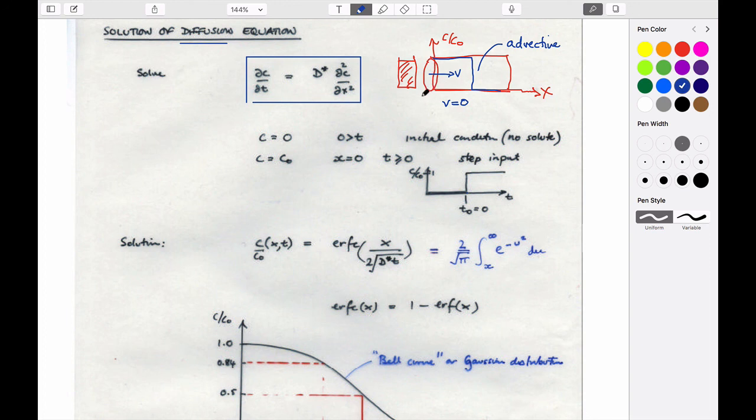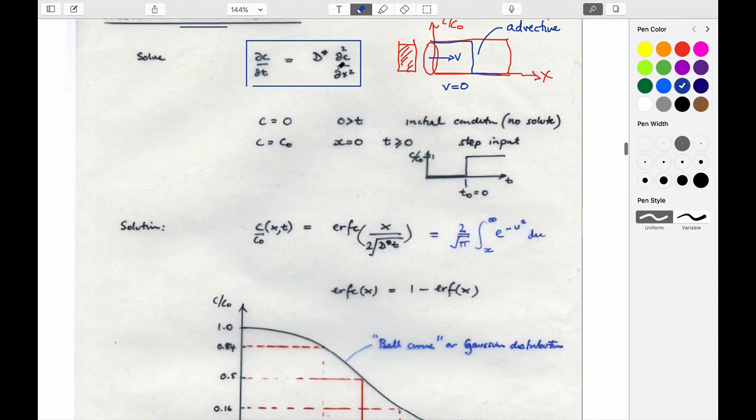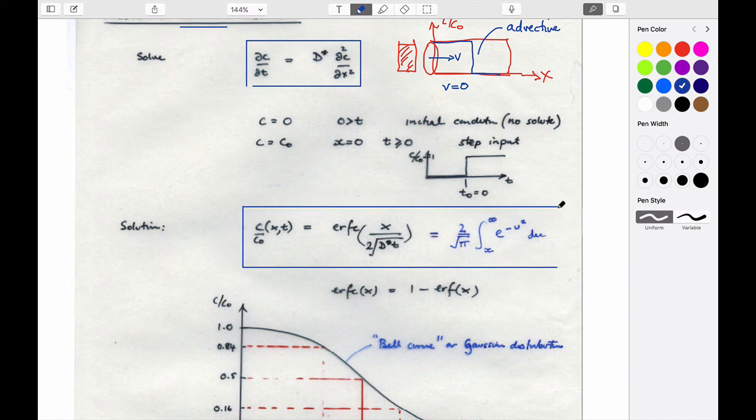It travels by diffusion. And so if you solve this equation for that particular boundary condition, turning it on at time t0, then the solution of it is this. Happens to be a standard result. I'm not sure you'd ever have to, we might play around with it in class. It's equal to the complementary error function for the distance downstream. So this would be the distance downstream. This would be when it would arrive. And this would be this effective diffusion coefficient.